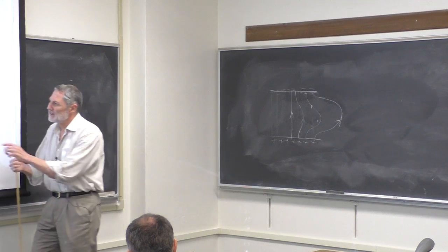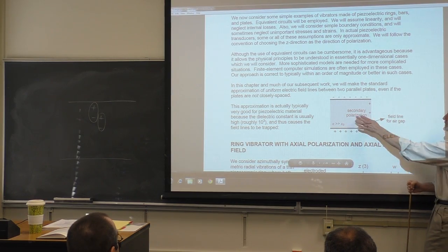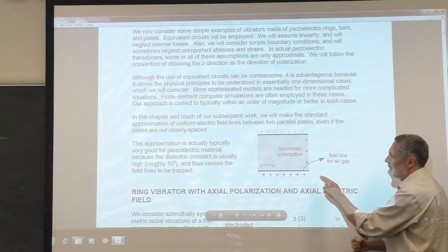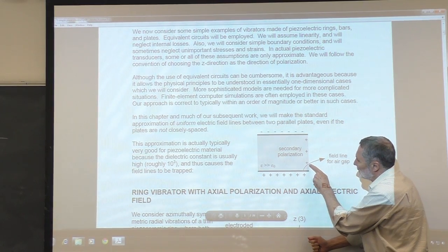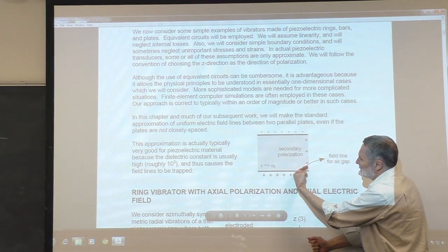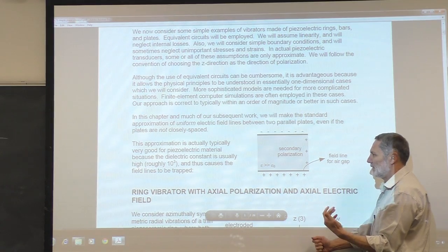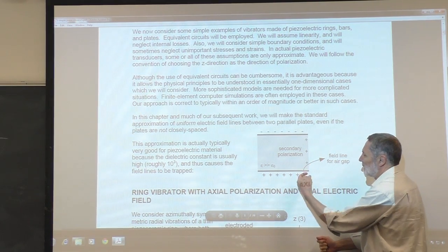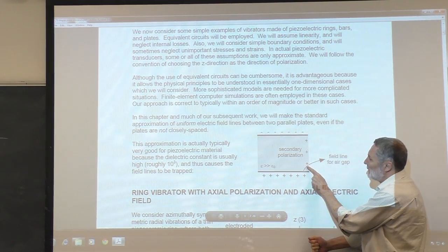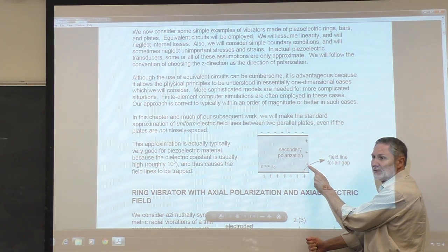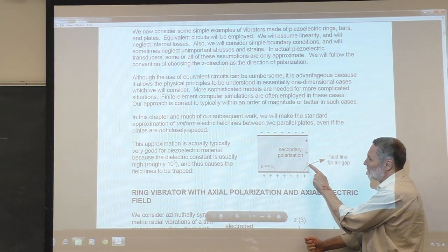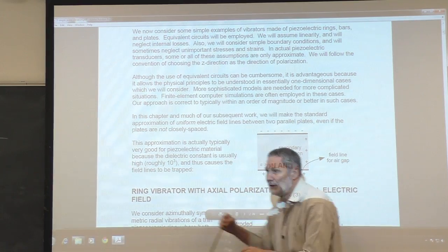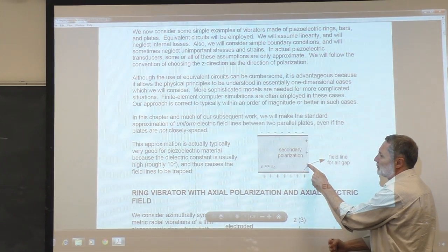And what's happening there is this. Here's a field line in the absence of the dielectric. Once you put the dielectric in there, imagine starting at time t equal to 0 with the dielectric there and this electric field. The electric field is going to cause a polarization, and because the electric field is in this direction, this will be plus.